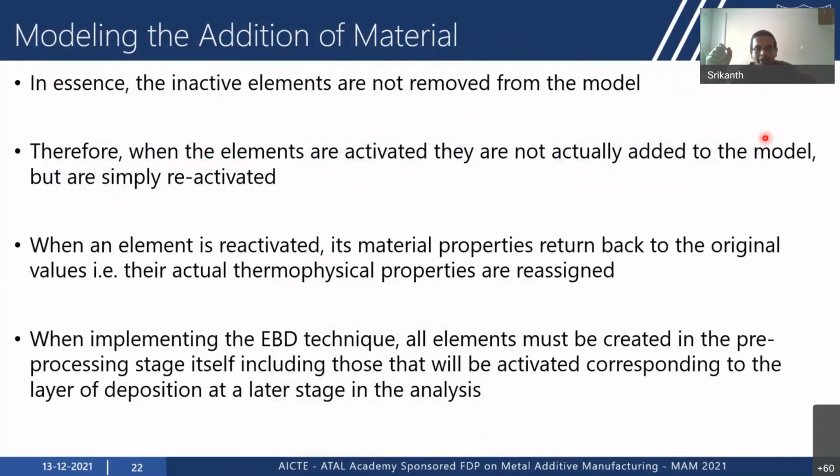So it is important to note that the inactive elements are not removed from the model. Okay. And how can they be activated once again? They can be activated once again by reassigning their original material properties, by reassigning their thermophysical properties back. Okay. So when we are implementing this EBD, or element birth and death technique, all the elements must be created in the pre-processing stage itself. And initially we kill all the elements except that of the substrate. And then as the deposition occurs, we keep activating the elements based on the location of the heat source.